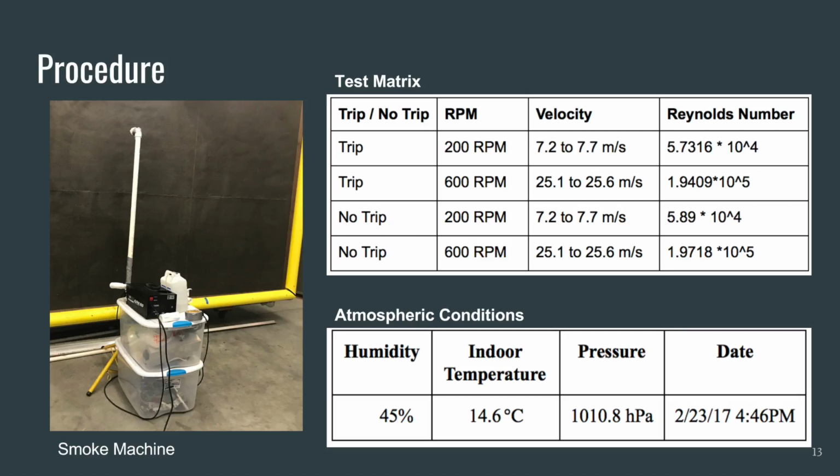First, the team reviewed the safe working procedure for the wind tunnel and noted the conditions in the lab. Then they measured and recorded the cylinder's dimensions and position in the tunnel. Throughout the experiment, the team took pictures of the pressure taps and noted any sources of potential error they observed. The team verified with the TA which transducer ports were static taps. Before turning the wind tunnel on, the team recorded wind-off data and atmospheric conditions.